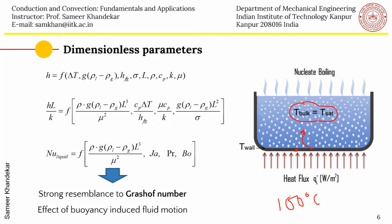So this is a typical tea making at home. The water first starts at room temperature, but then fully developed nucleate boiling will start at 100 degrees centigrade bulk temperature. So there is a delta T. Then the bubbles are formed. Bubbles are lighter than the bulk liquid, so naturally the density of the vapor is lower. So the bubbles will tend to rise upwards. So there is a buoyancy force, g delta rho, which is affecting the process.